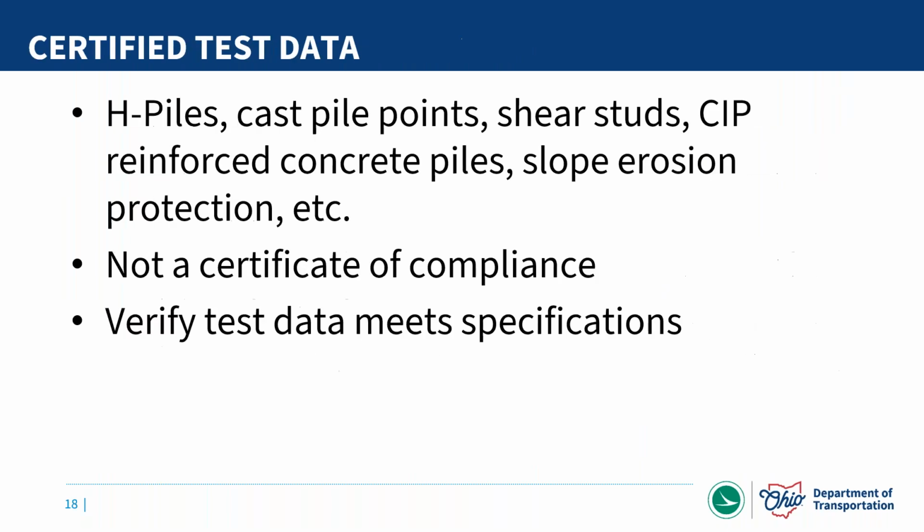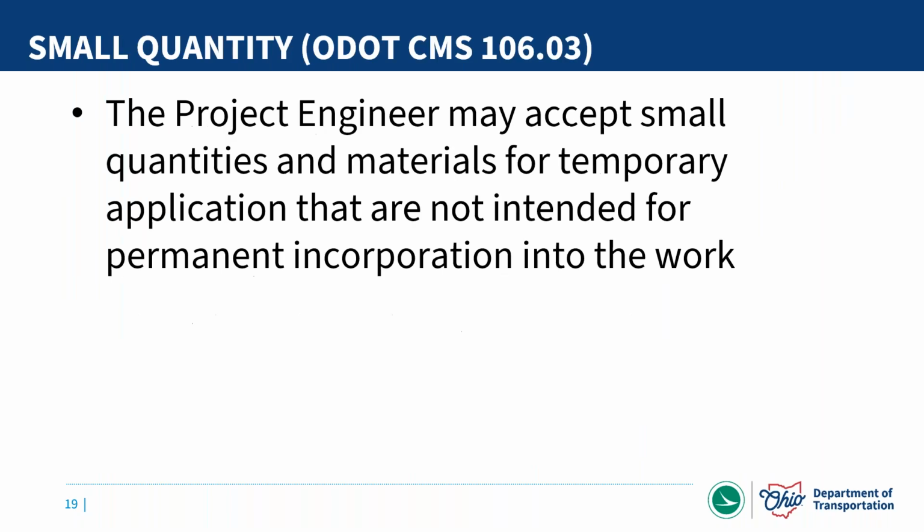Another material acceptance method is certified test data. This includes H-piles, cast point piles, shear studs, cast in place reinforced concrete piles, slope erosion protection, many other items. This is not a certificate of compliance, and test data still needs to be verified to make sure that it meets specifications.